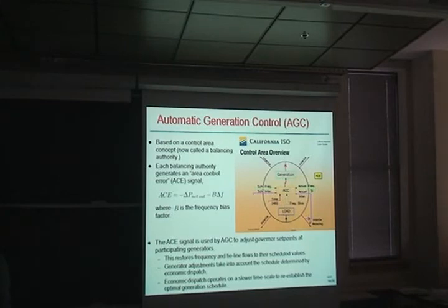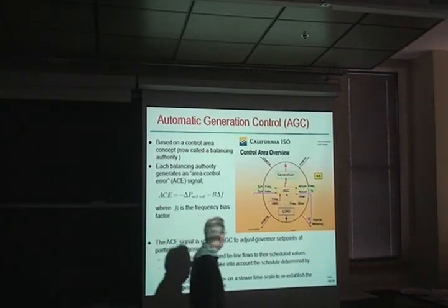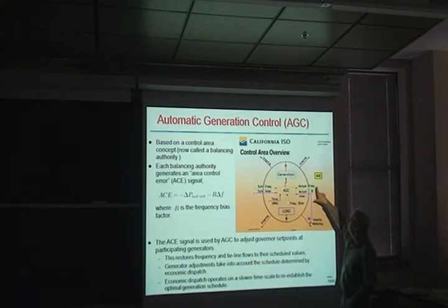as they were putting the load back together again, to match these big chunks of load that were coming into service with available generation. And with the transmission, that some of it was out of service because it had been broken, other bits were in service, so they had to use what was available to try and re-energize pieces of the network. It's quite a challenge. There's no automated process for doing that.